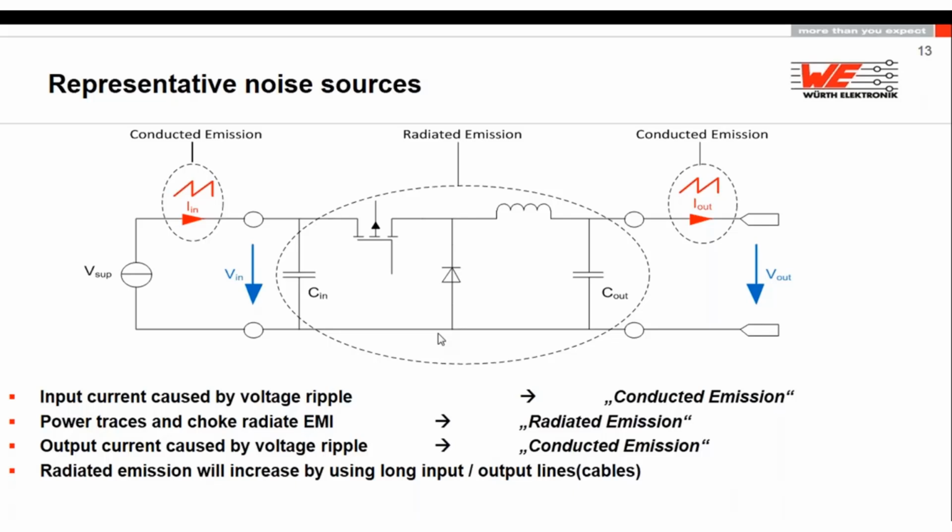Please take care that this track is as short as possible, as low impedance as possible, because this is your major radiation point in the anechoic chamber. As soon as you keep this antenna as small as possible, this is very welcome. And think about it: 1 millimeter of PCB track is exactly 1 nanohenry. So, perfect inductance.